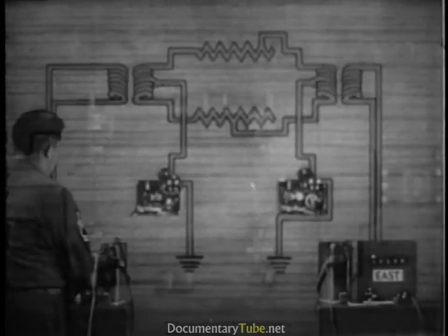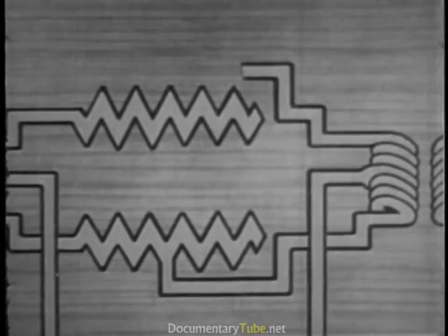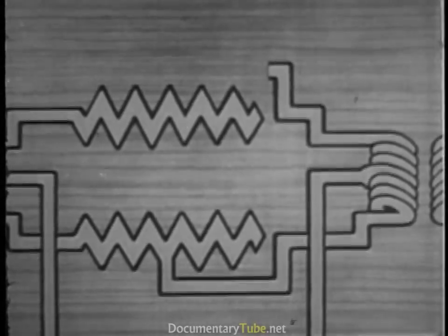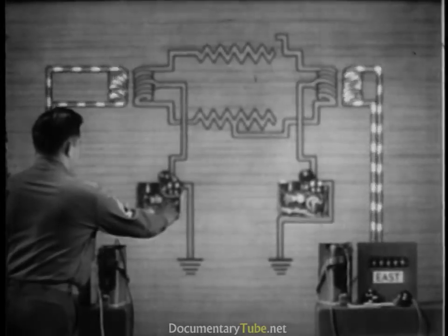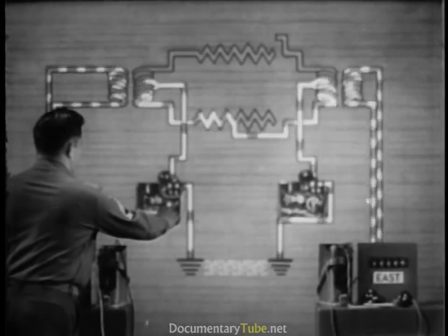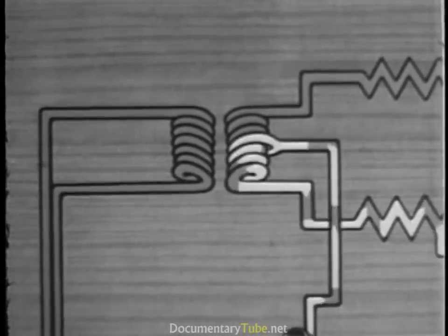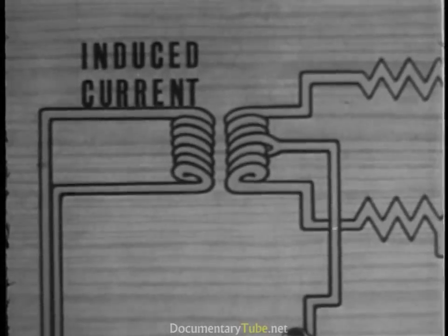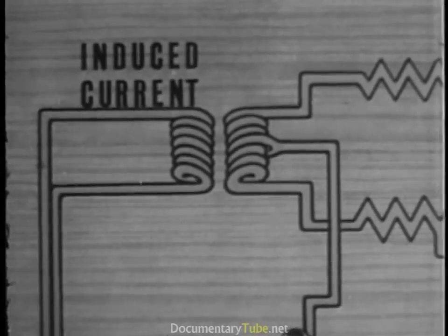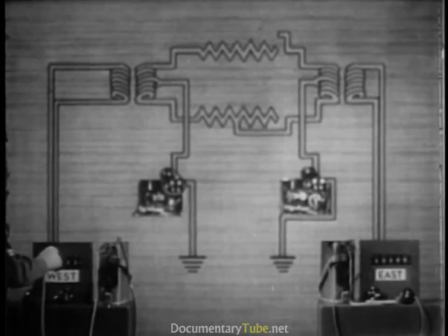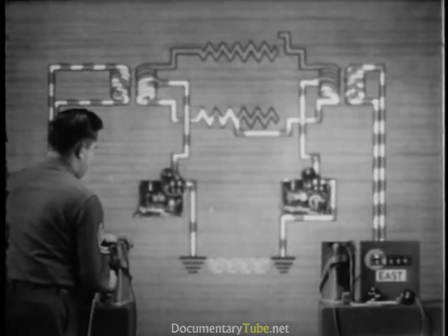The extreme condition of this unbalance occurs when one line wire is open. Now, all the telegraph current travels over one wire. And the current induced in the telephone circuit is at a maximum. Telephone signaling is still possible, even with the open line wire.